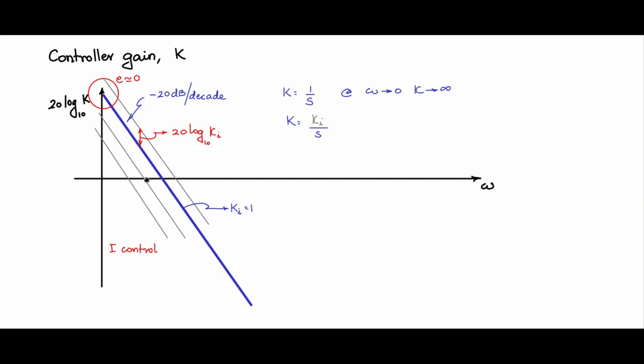Now you see the points of intersection. This is the unity gain bandwidth product. So when you compare this parallel intersection with respect to the blue line that we have selected, you see that this parallel is having a higher gain bandwidth. The one here has a lower gain bandwidth. The one here has still lower gain bandwidth. So the speed of response is the one that is going to be affected by choosing the parallels.